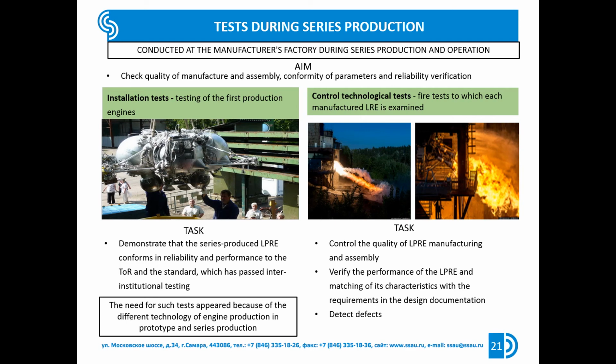The purpose of the installation tests is to show that the series-produced liquid propellant rocket engine conforms in terms of reliability and performance to the technical specification and the reference, since the technological process of producing a series-produced LPRE always differs from the process of producing it in the prototype production. The applied methods of control of commercially produced liquid propellant rocket engines largely depend on their purpose and design features, the fuel components used, etc.